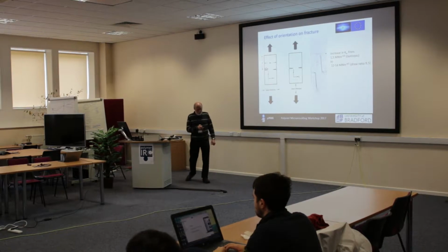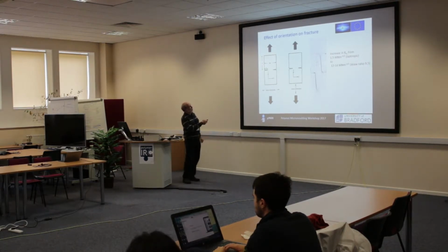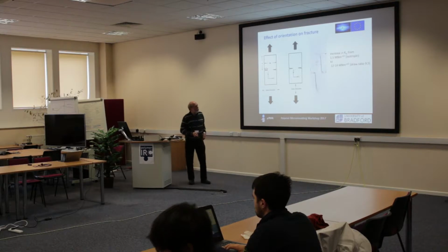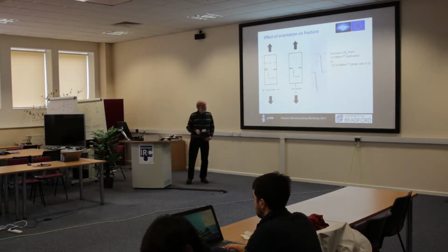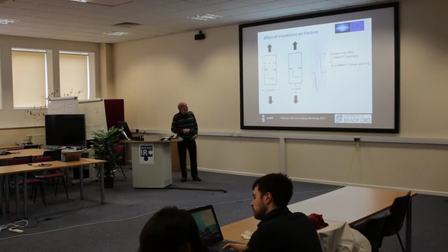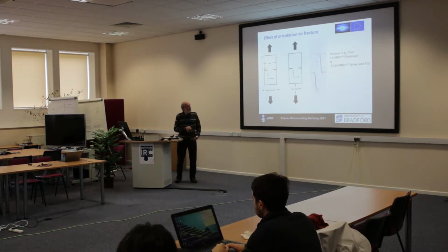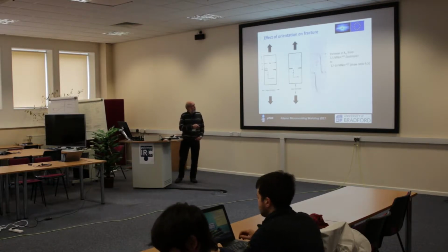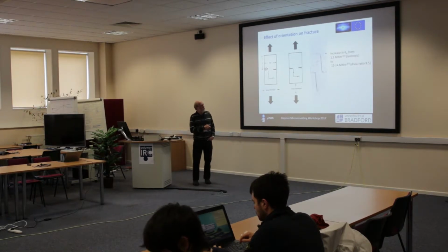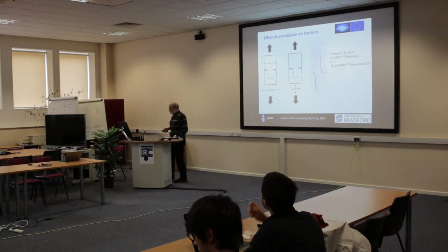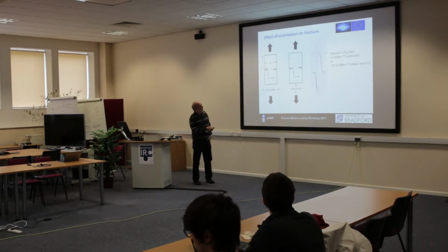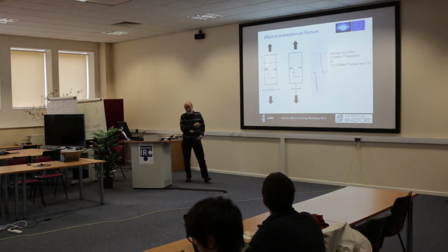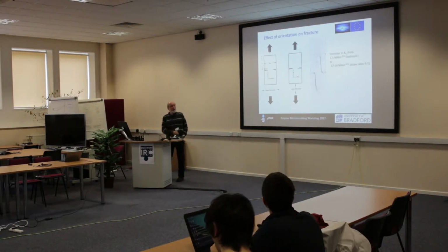So you change, and of course, this one just cracks straight across like an undrawn material. And we don't actually improve. You may improve some fracture toughness slightly in that direction, but not much. So the isotropic value for K1C is 1.5, and you almost increase that by a factor of 10 by this drawing. And of course, it's around 10, the draw ratio here. And this was done by die drawing, strip die drawing. The material is actually polyethylene.